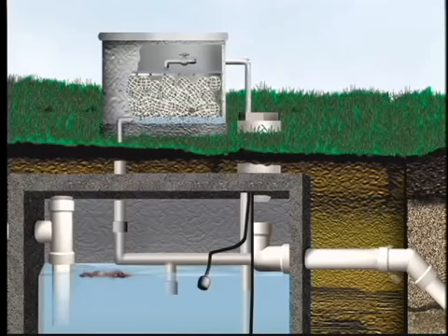A constructed wetland is designed to mimic nature's own processes, using plants and microbes to treat wastewater. One major difference is that in a natural wetland, water is generally visible in the system, while in a residential constructed wetland, the water flow is maintained at a subsurface level. This system consists of a septic tank, constructed wetland bed, and land application system. These systems are designed to blend into and even enhance a landscape design.